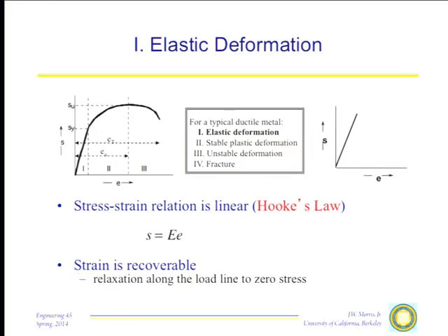In elasticity, we get that same kind of simplification. It's a little bit more complicated because we're dealing with second-order tensors rather than vectors. But in fact, if we take a cubic material, there are not 36 independent elastic moduli. There are only 3. And if we go to the case that we most commonly have in engineering, where we have an elastically isotropic material, either because it's an amorphous material like a glass or polymer, or because it's a polygranular solid, then we only have 2 independent elastic moduli. And we'll assume that that's the case.